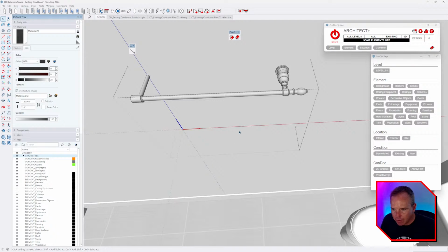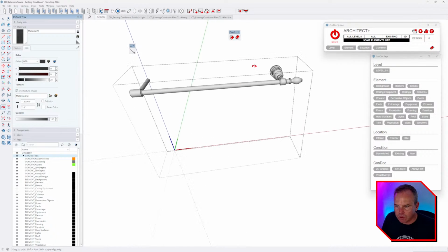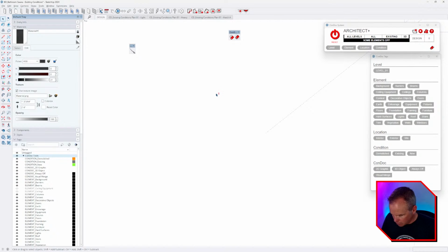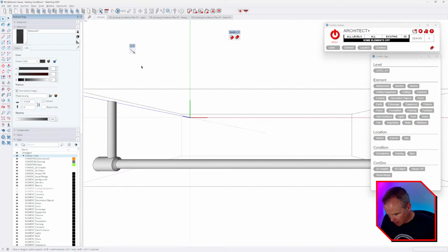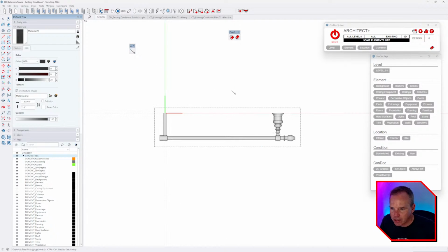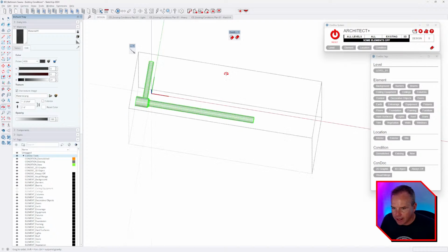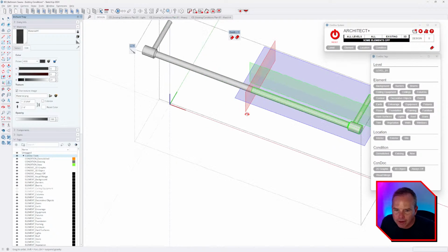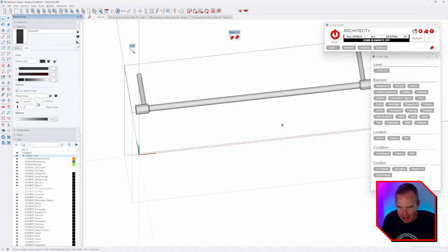And then perhaps I would hide rest of model, and then go to plan view, zoom extents, parallel projection, get back to Zorro and just slice it, and then kill this, and all this. Again, we can use our lovely flip tool, and now flip it like that, and then get rid of that.